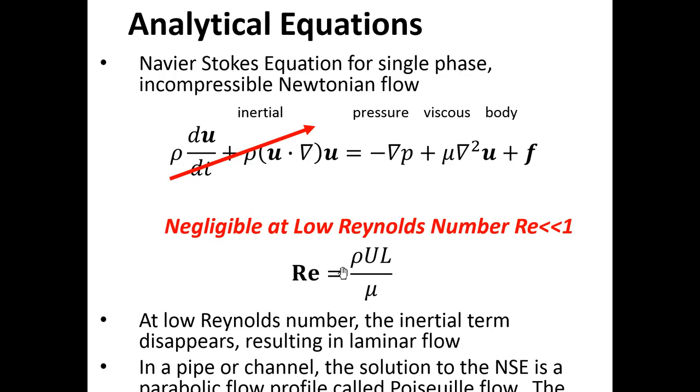So how does this scale to the microscale? This is a function of L. In a microfluidic device, the Reynolds number drops precipitously. Not only does L go down, but in a really tiny channel, the velocity of the liquid is going to be smaller than in a very large pipe.